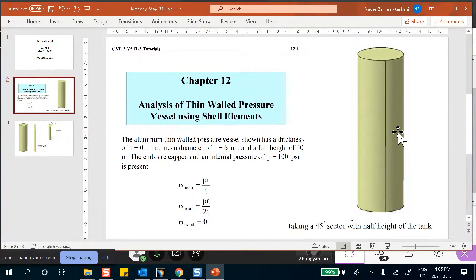Just a comment, in a stress analysis course, not the one that you took though, the advanced or intermediate version of it, you also discuss thick-walled cylinders. In thick-walled cylinders, the thickness is not so small that we can ignore the pressure, saying that it goes from, I don't know, 100 to zero. If that is thick, that pressure may be significant, and you have to consider that.